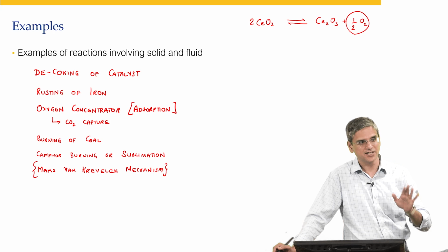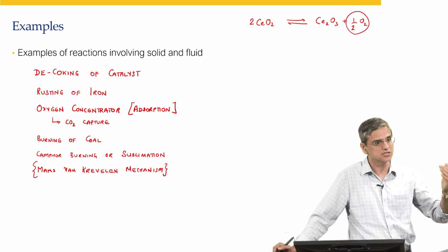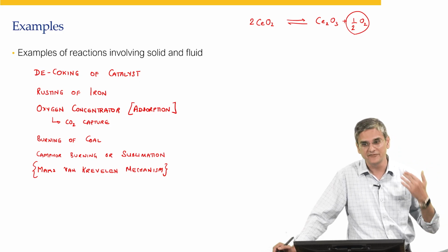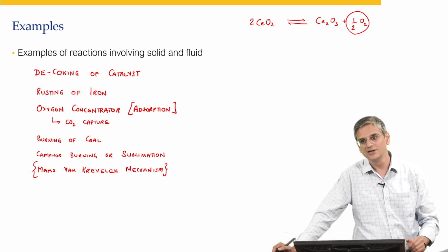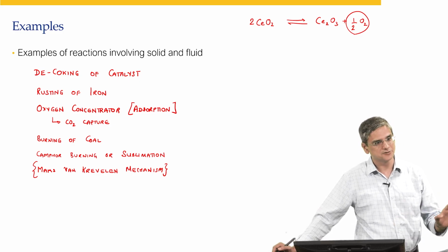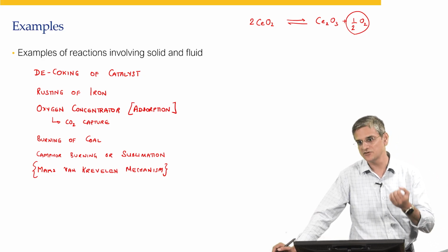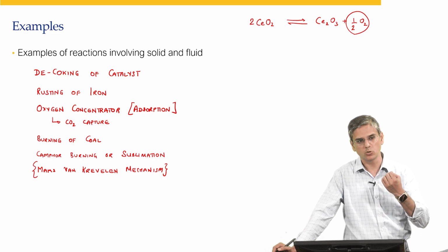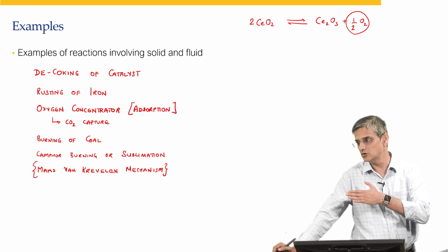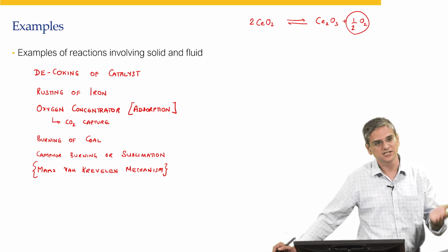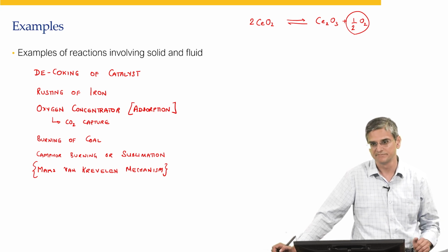So every time a car brakes, if ceria was not there in the catalytic converter, you would have seen smoke every time a car brakes and every time a vehicle accelerates. In the old vehicles, you would have seen it during vehicle acceleration, that's the smoke coming out, right? This is the presence of what is called a particulate filter that prevents the smoke from coming out, and it's the presence of ceria that prevents hydrocarbons from coming out whenever you have a braking event.